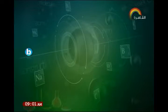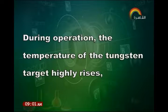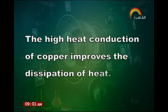What about the use of the copper block in the tube? During operation of the device, the temperature of the tungsten target rises highly. The high heat conduction of copper improves the dissipation of heat. So we need to get rid of the heat produced. We use copper because it is simply a good conductor of heat, so it dissipates the produced heat to the surroundings.